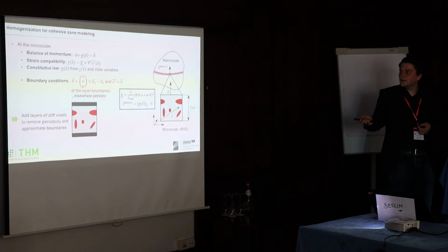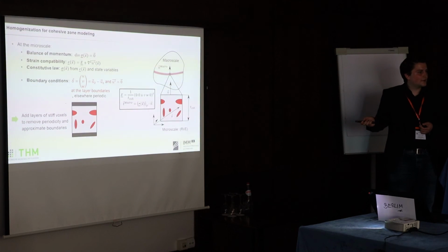And also, if you use this separation here, you can compute an average strain, or you can estimate an average strain according to this equation here. It's a Voigt notation, and then the microscopic equation becomes just this equation here, just the volumetric average multiplied by the orientation. In this case, the orientation is just the 3 ring.